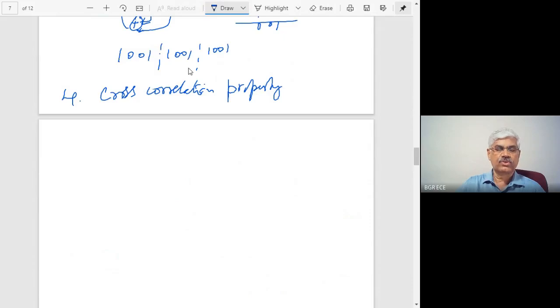And the number of codes that can be generated with a given length of shift register is also a concern. So that is also a design parameter. Now, PN sequence allows you to generate a certain number of codes in a given shift register, whereas Gold codes allow you to generate more codes with a given length of the shift register, with a small compromise on the autocorrelation value, cross correlation value, and so on.